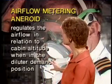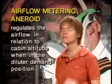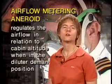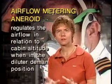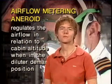Now, you will have very typically an airflow metering aneroid in the demand regulators on this type of oxygen mask. And the purpose of that airflow metering aneroid is to regulate the airflow in relation to the cabin altitude when the mask is set in the diluter demand position.